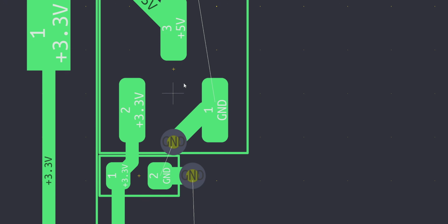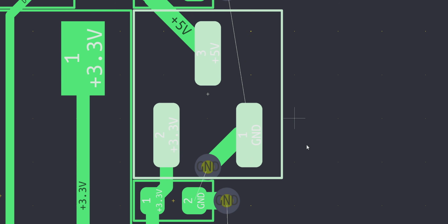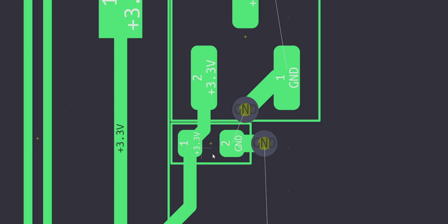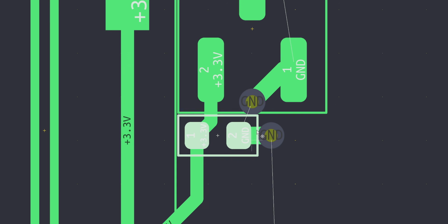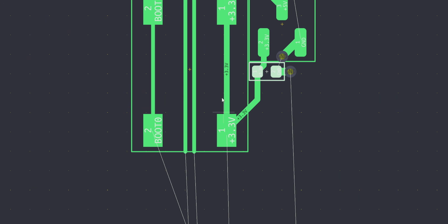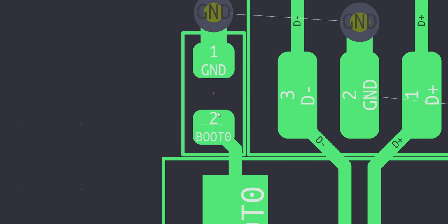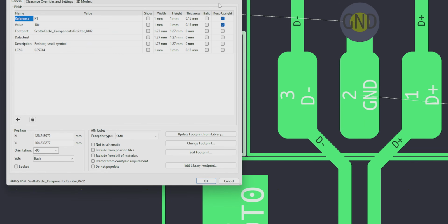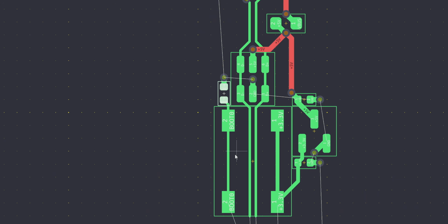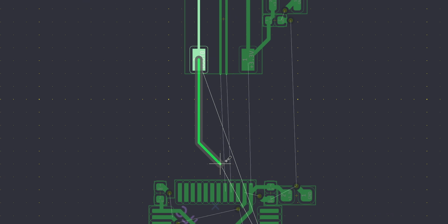But finally, if we just look at our power circuit over here again, you can see we grounded out on 1 pin. We have our 3V3 out. This is that stabilizing capacitor to stabilize that voltage. And then we feed that into our reset button here. So we have 3V3 on the reset button. We have our boot pin. This is supposed to connect to the boot pin over here. That is connecting to this, I believe, is this a resistor or a capacitor? If I double click that, it will tell me that is a resistor. That's just feeding to ground here. And then off of here, we can feed this down to our MCU.